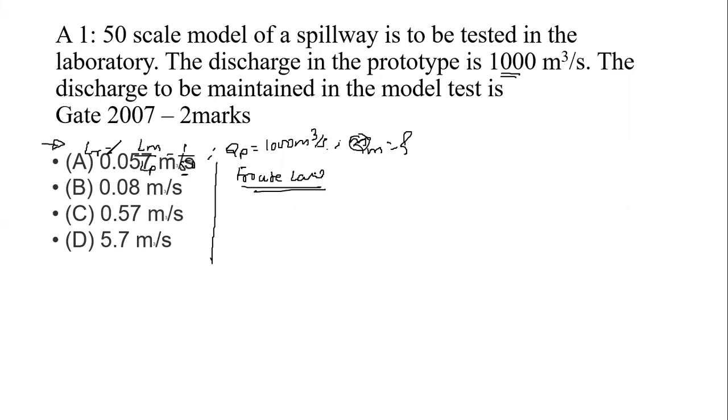Froude law will be the best. But why? Froude law के हिसाब से इसका मॉडल क्यों प्रिपेयर किया जाएगा? Because this is the spillway. Means the water is flowing over the spillway under gravity. Free surface flowing water is there. So Froude model law will be used.